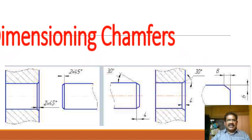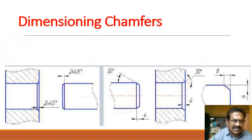Okay, next is the dimensioning of chamfers. Chamfer dimensioning is shown here. Chamfering is done at a corner to remove a sharp edge at a joint. The edge is made into a small flat, and this one is 2 mm with 45 degrees. This is an internal chamfer. This is an external chamfer.